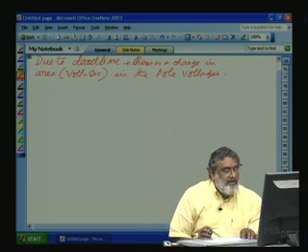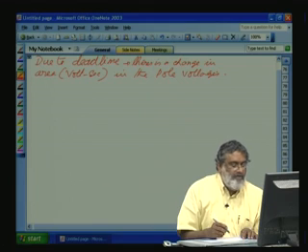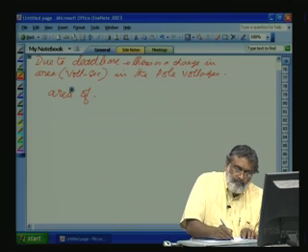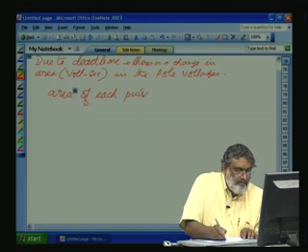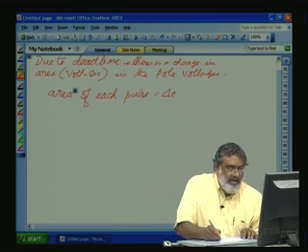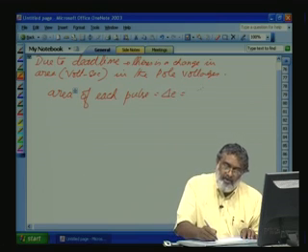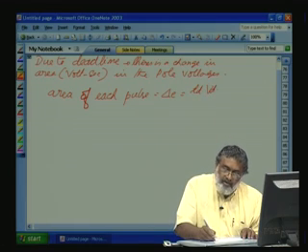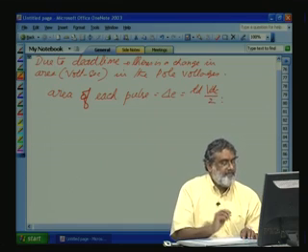So, how it can affect? What is the area of each pulse? Let us say the area of each pulse, that is delta E, is equal to TD, that is the dead time, into VDC by 2.